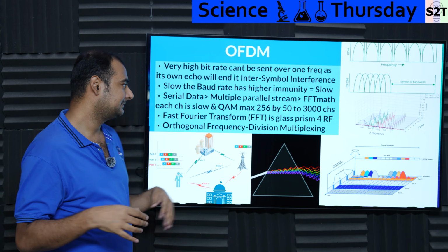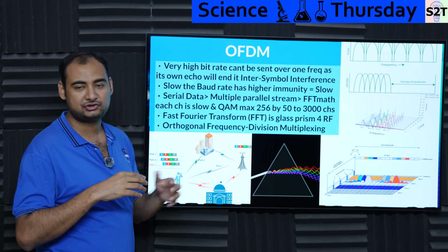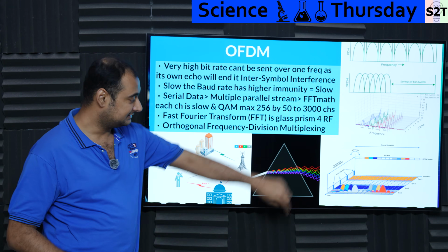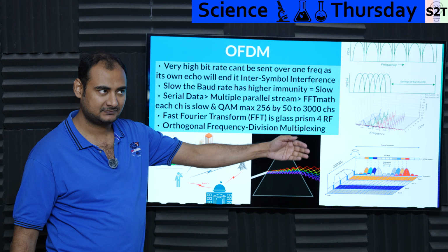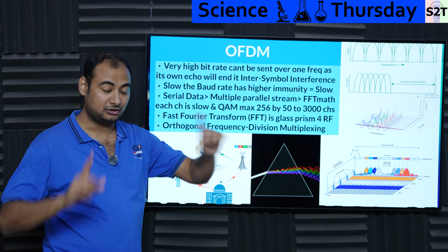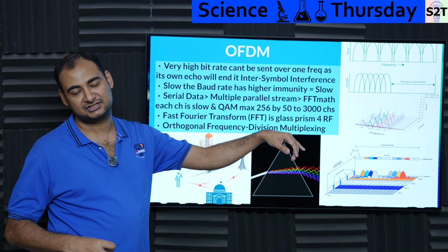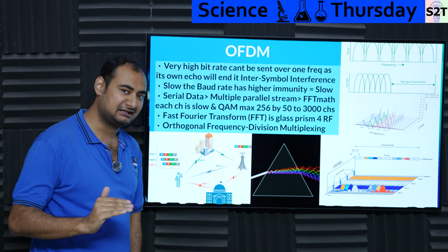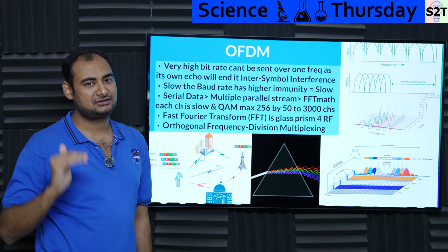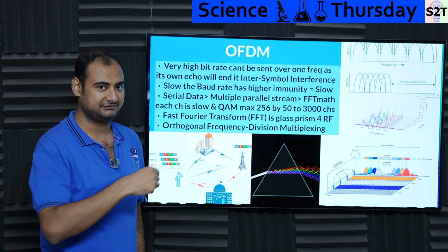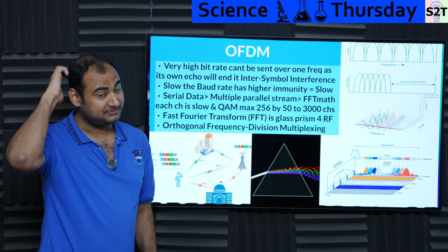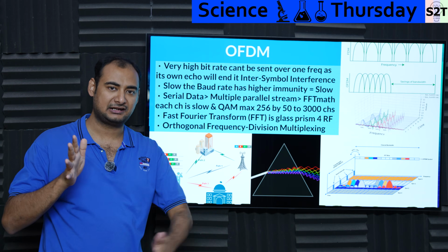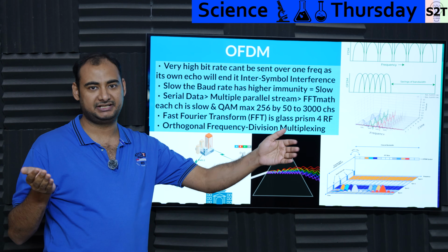So you take that many streams and then you apply a magic. Now here's the deal. That stream mathematics you did, it's getting encoded into radio waves, but not on a hardware level. This is happening like the colors of a white light. Basically, you are doing that in a mathematical domain, which we call the Fourier transform, fast Fourier transform. You are mathematically doing it, like, what if I have to send 3000 channels of data, each channel should have two domains of data, I and Q that we have already talked about, symbols, you are basically sending symbols, but it's just that each is slow. Each channel is slow, but you are sending so many channels, you are parallelizing it and the speed is very high.